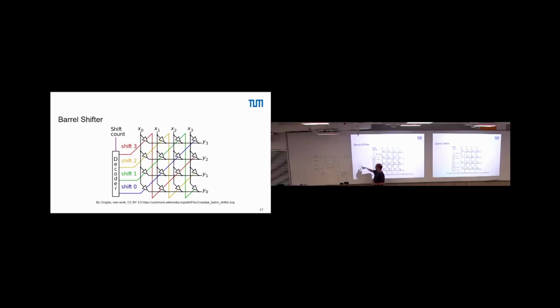Because here's an inverter, we have this for both. If the select signal goes down, we have no connection. That's it. The purpose of having NMOS and PMOS is that we want to have full swing from 0 to VDD. But we don't need to go into detail. And such a thing effectively is such a block in the diagram. So it's just a switch.